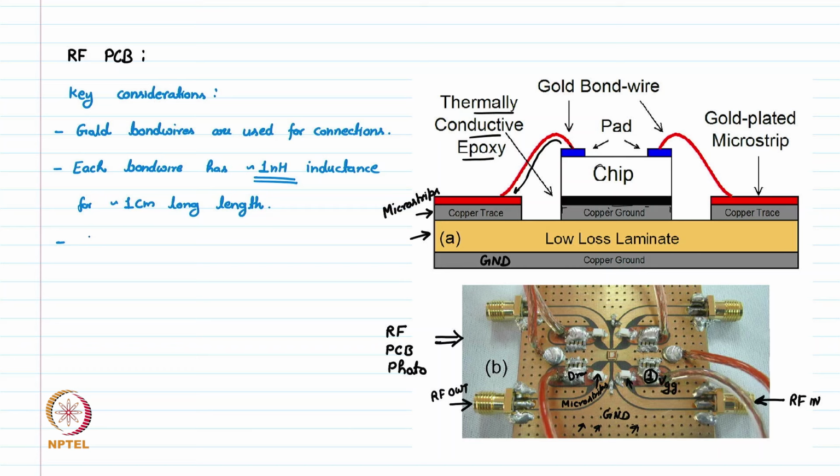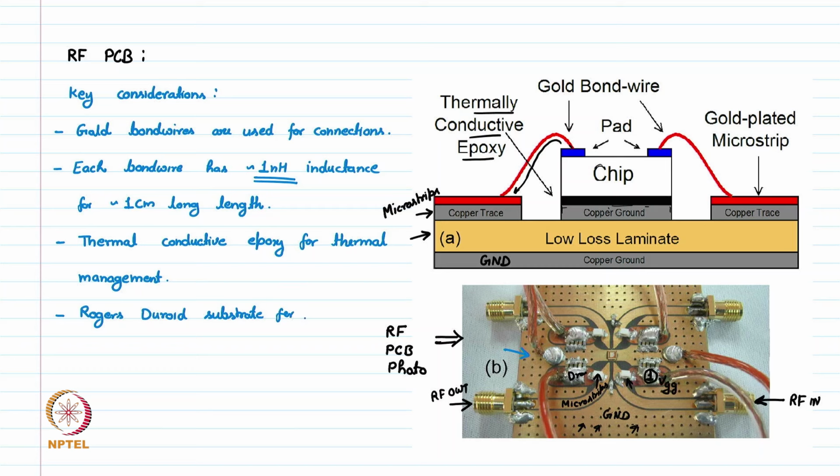Here we use thermal conductive epoxy for thermal management. The substrate here is not FR4, it is Rogers Duroid substrate, for low RF loss.